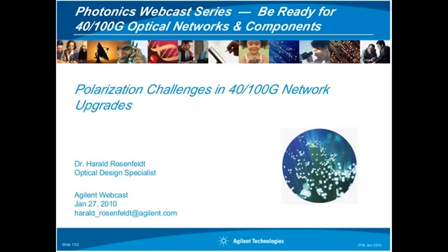Today we will discuss tackling polarization mode dispersion, PMD, which has been considered a key challenge when moving on to today's bit rates, such as 40 gigabits per second or 100 gigabits per second. While PMD compensation seems to be unavoidable for RZ and NRZ transmission, new modulation formats such as QPSK, DQPSK promise to provide inherently higher PMD tolerance. In particular, complex receiver schemes incorporating adaptive hardware need to prove their tolerance against various dynamic impairments.